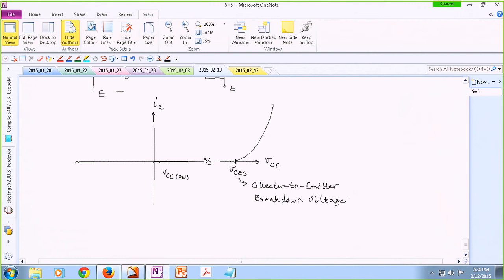So for instance, when you buy a 600 volt IGBT, that 600 is referring to this parameter. That means while your device is off, you can expect your IGBT to tolerate 600 volts without breaking, okay? All right. Now, what about negative voltages? How about if I apply a negative voltage to my IGBT? Again, for a certain range, you're okay, and then the device breaks.